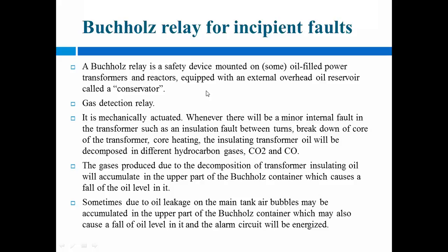So these incipient faults are the slowly developing faults. Incipient faults means slowly developing faults. These faults occur in transformers, and to protect the transformer from these incipient faults, that is slowly developing faults, we are using this Buchholz relay.